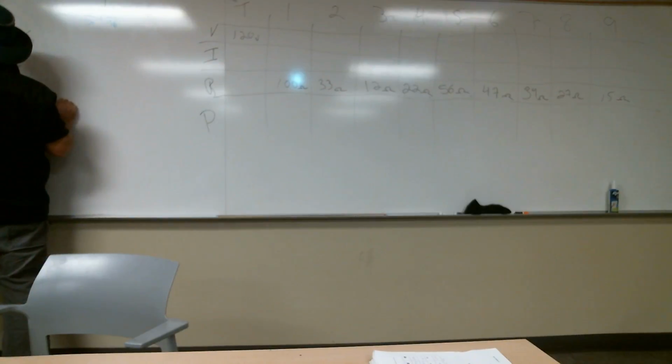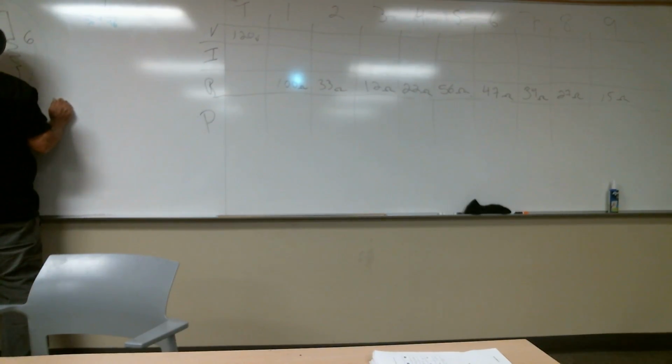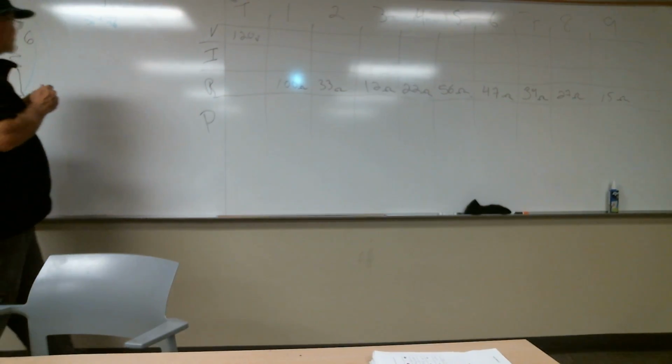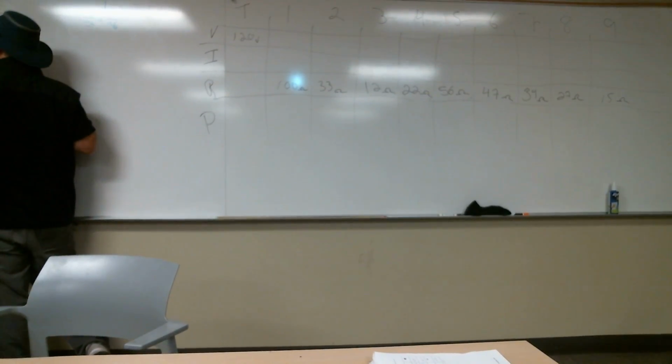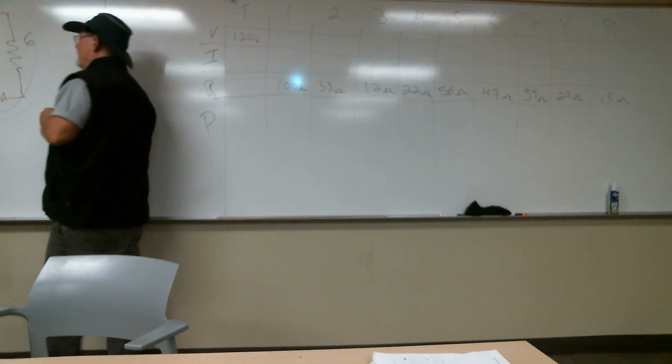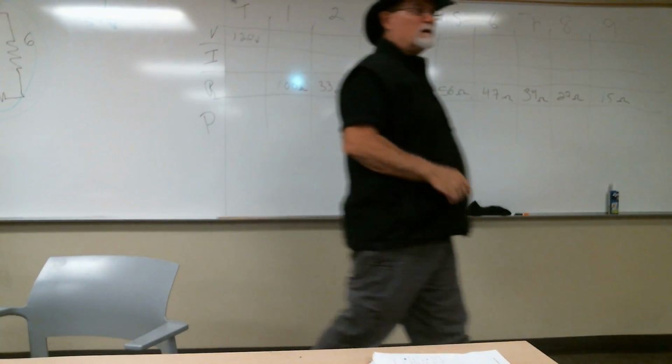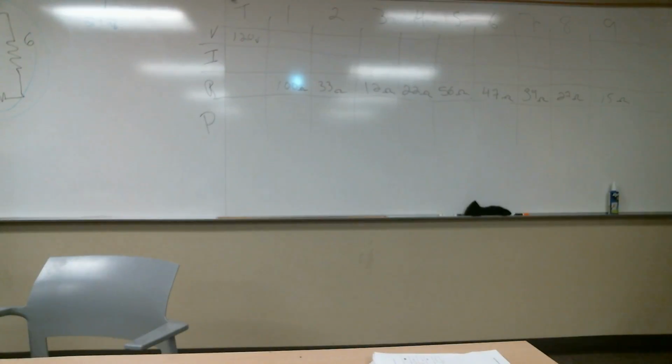So we can say all of this equals 35.6. Give me a couple more. 63. Well, we can say 6. That way we're not truncating. Oh, I forgot my little homies. Okay, so we can say that equals 35.636. If I combine all 5, 3, 6, and 7 into one resistance value, that equals 35.636.